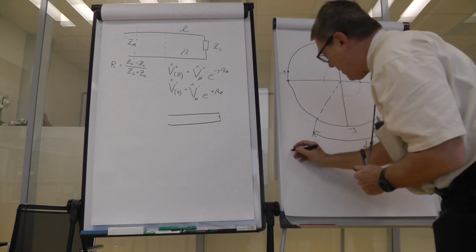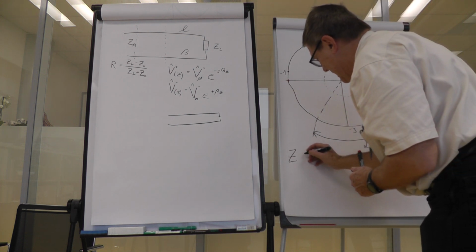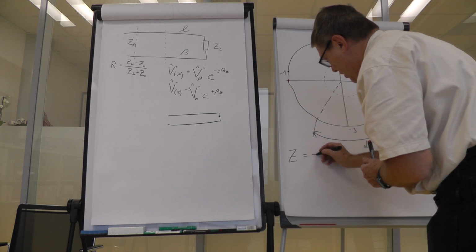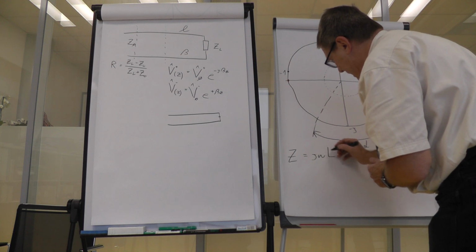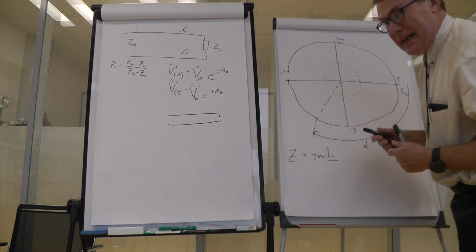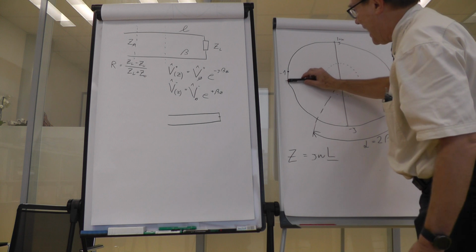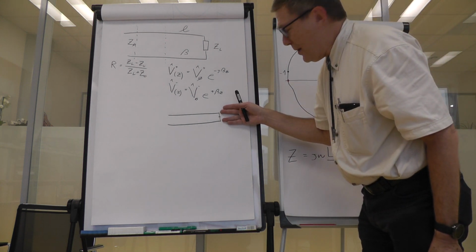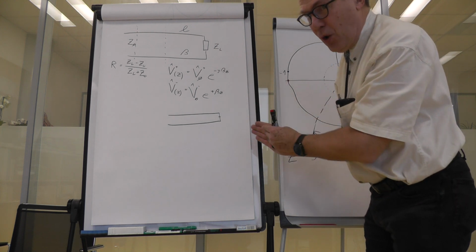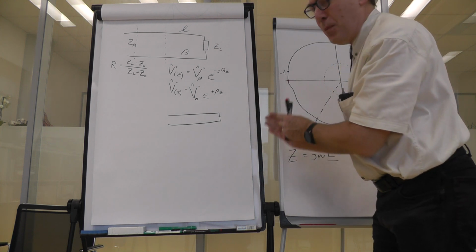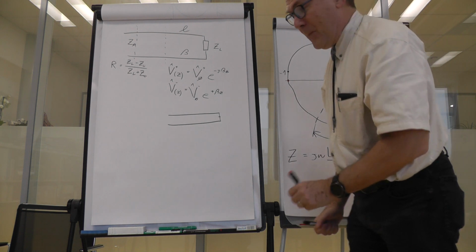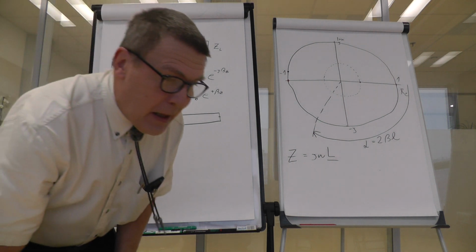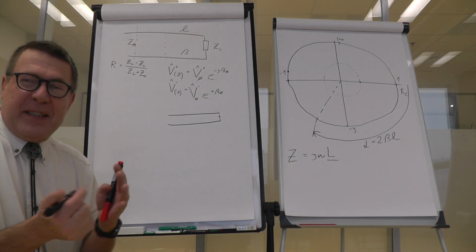Well, okay, if the Z is purely imaginary, we could interpret it like j omega L, where L is an inductance. So in fact, any short current path which is intended to be a short is in fact a small inductance. And a small inductance is something that could be dangerous. Let's say, to have a small example,